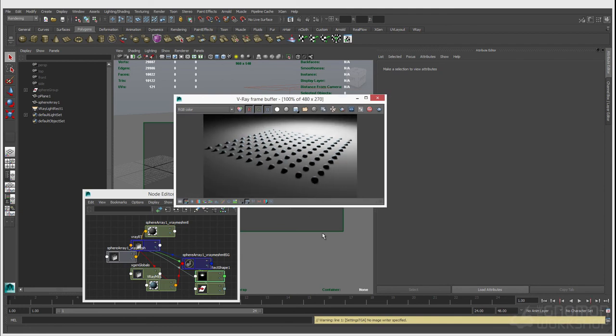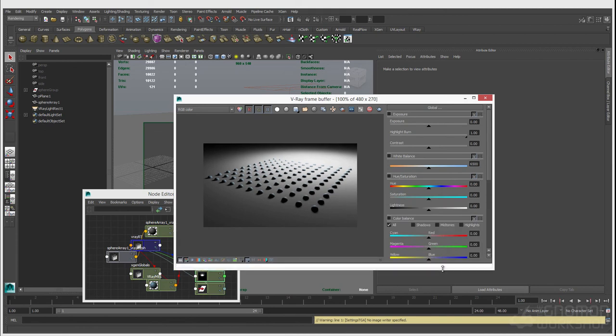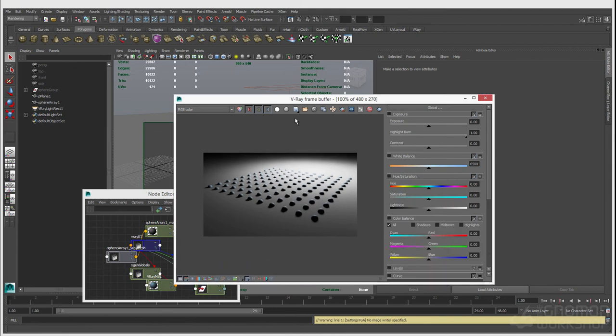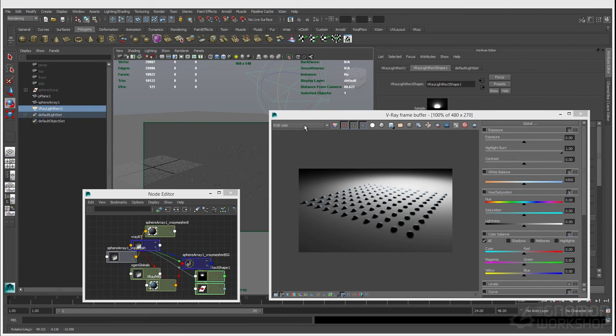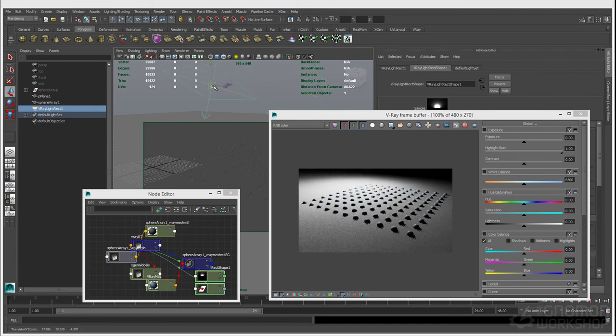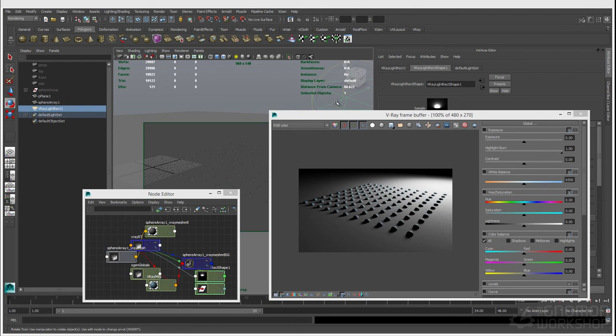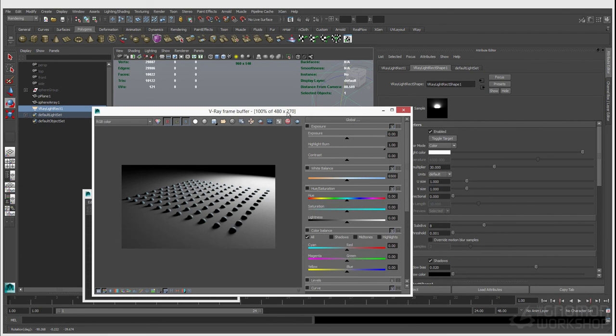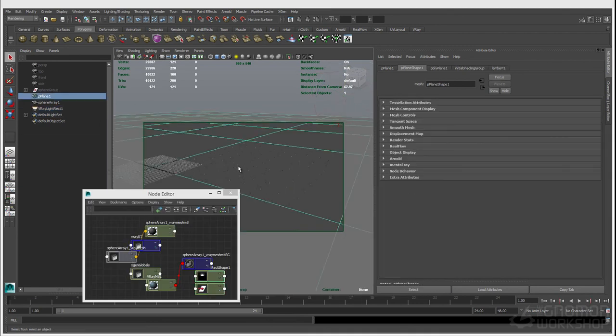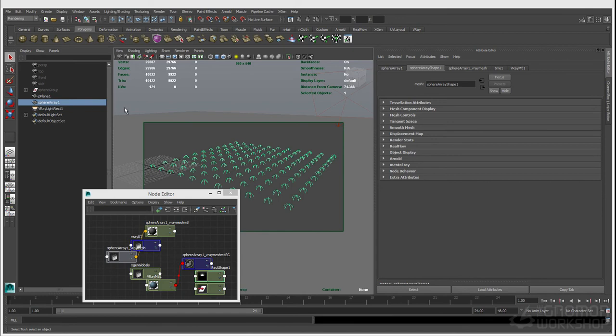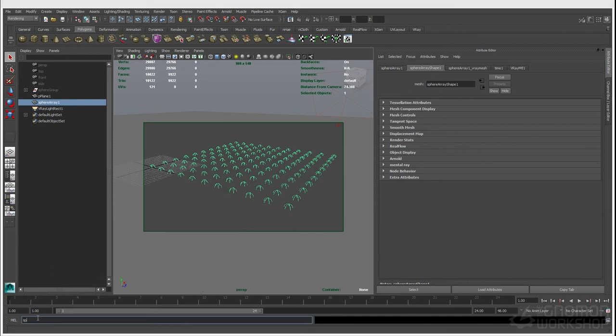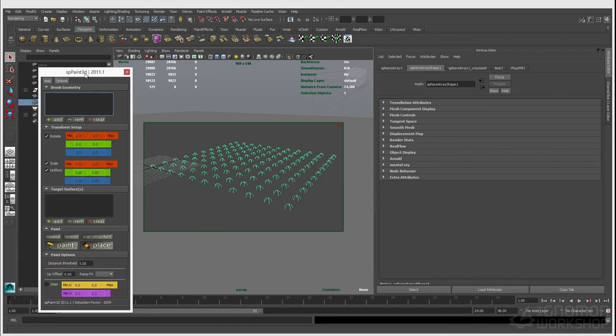So let's turn our quick LUT on. You can see I've got a simple 1D LUT to kind of even this out. But yeah, pretty amazing how fast that can be. Still reacting very, very responsively. And maybe we'll go ahead and make this a little bit crazier even. Because this is still a regular Maya shape node connected to a V-Ray mesh node, I can actually instance this as well. So again, I can pull up something like SP Paint. I could instance these across particles. You can do all sorts of cool stuff with this.